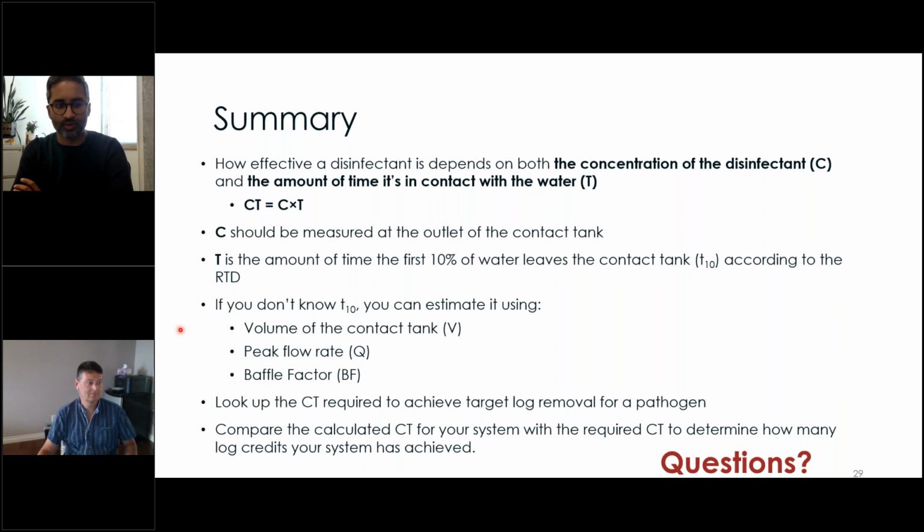And that really just has to do with you're adding chlorine, it's reacting, the amount of free chlorine getting used up until all those reactive species have formed, and then you have the free chlorine that's available to do the disinfection. It's not entirely a different concept. So in the case of how breakpoint would affect this, it's really about the residual chlorine that's left over after your contact basin. So once you're supplying free chlorine, you're making sure that you're adding enough to overcome any species in the water that are going to react with that.